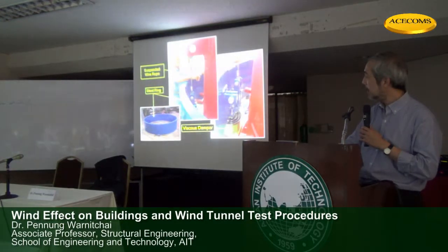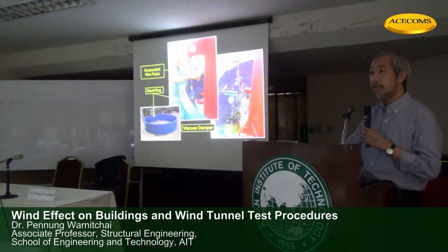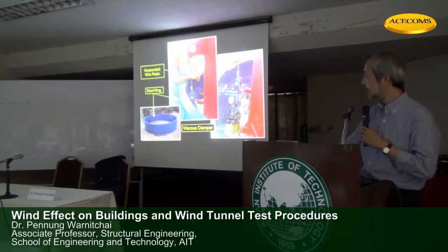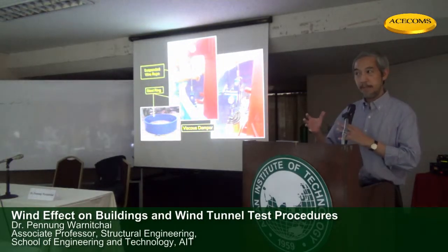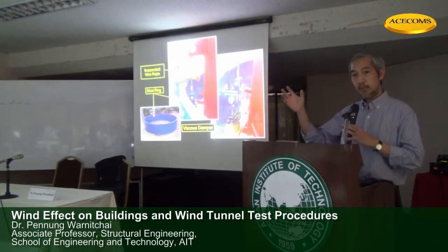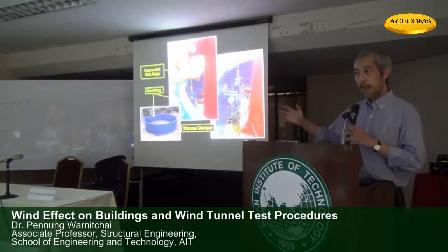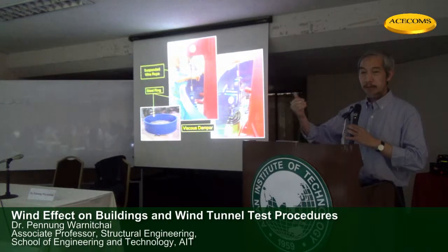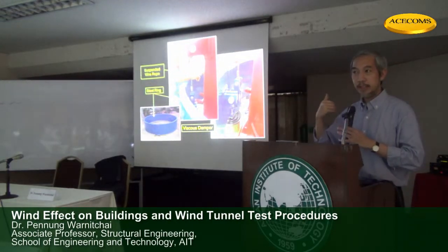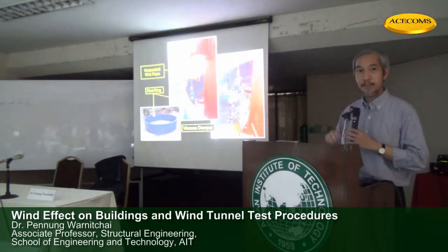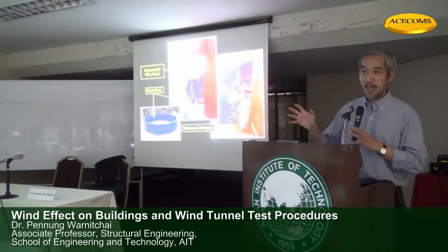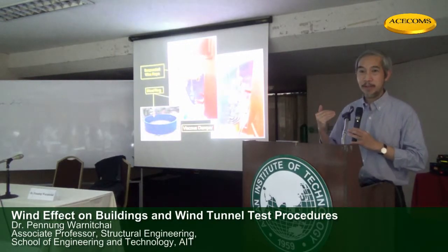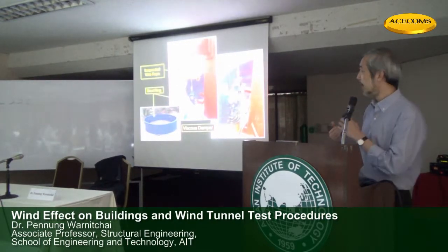It's in the factory, hanging by wire rope at 3 corners and attached with viscous dampers. This ring is kind of a pendulum. When the stack starts to oscillate, the ring will move more and will produce an opposite direction force to suppress the oscillation. So this is the kind we call this damper. When the structure starts to move, this will damp out the motion.